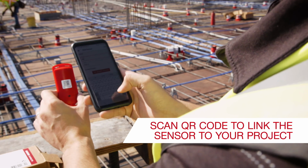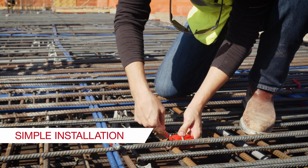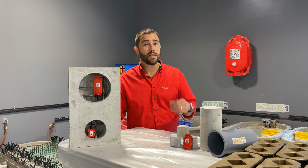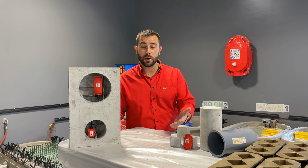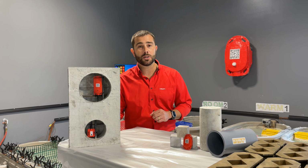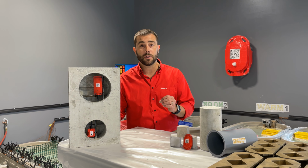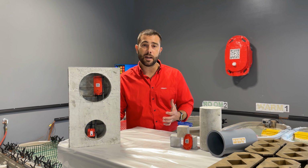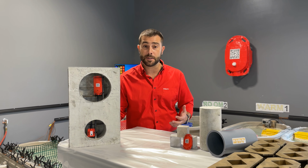Moving on to step 3, grab some sensors. You're going to activate them, install them, and then pour your concrete. Once your concrete is poured, the sensors will start to collect data, and then all you need to do is look at the data in the app, which will allow you to better understand the in-situ strength development of your concrete. Now, it's important to note that in most cases, code is going to require that cylinder breaks are done at certain time intervals. But now that you have real-time data at your fingertips, you can make better decisions about critical construction processes.